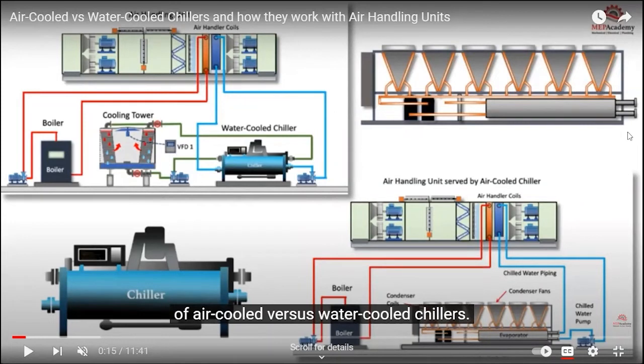And here we have the air-cooled chiller. So we have the water-cooled and the air-cooled. The water-cooled are usually monsters that are in the basement, and then we need a cooling tower on the roof. This monster is just on the roof. So here we basically combine both things. We have a heat pump, and then something that exchanges heat with the air. In this case, both things are in the same machine.